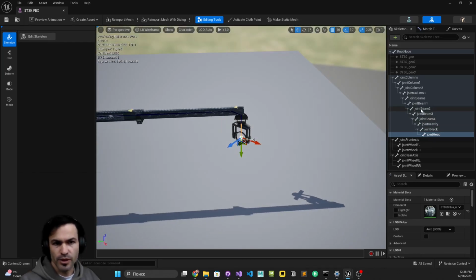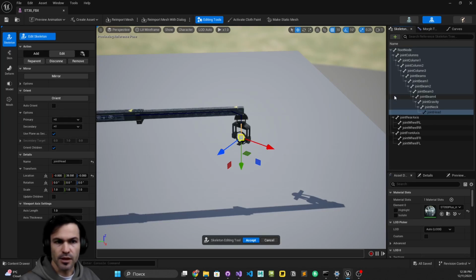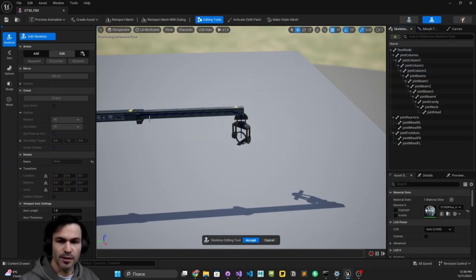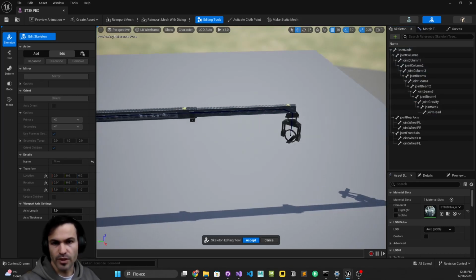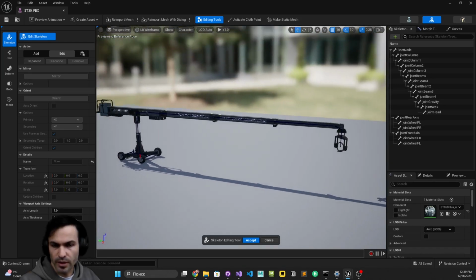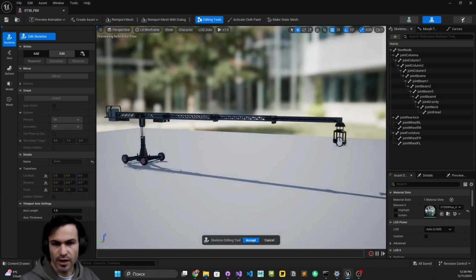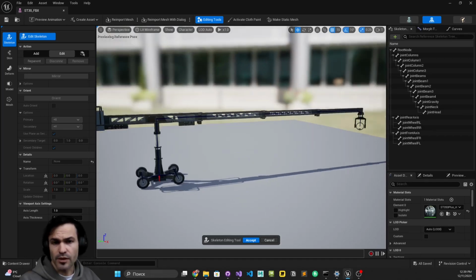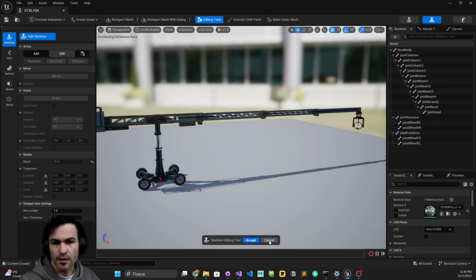And one small tip: if you edit a skeleton and go to another model where these bones already have the correct hierarchy, you always have the possibility to select the bones, copy them, and then paste into another model. That's also the trick I've used to be precise on this alignment of the final bones. Yeah, so I think that's it for our skeleton.